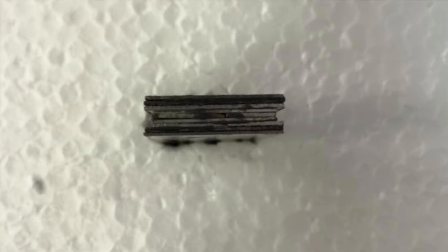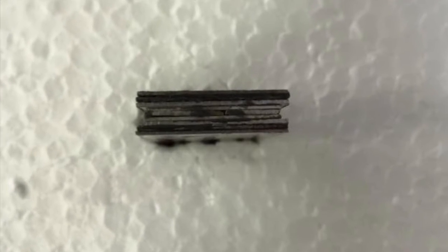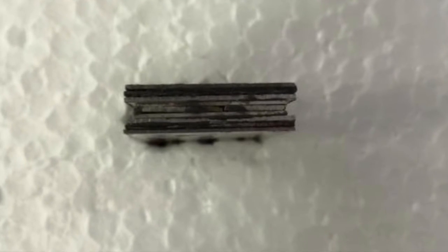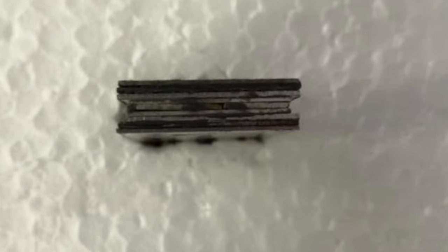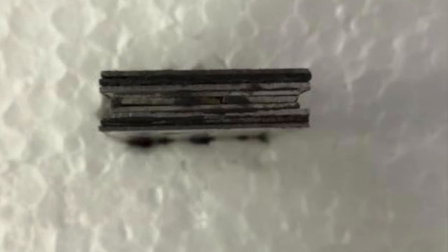Fourth, for the brass plate, we do not want it because the yield strength of brass is nearly that of aluminum, but the density is 3 times more than aluminum, so we do not want much brass in our beam. We set it at the core of the beam and reduce its dimensions as shown in the figure.